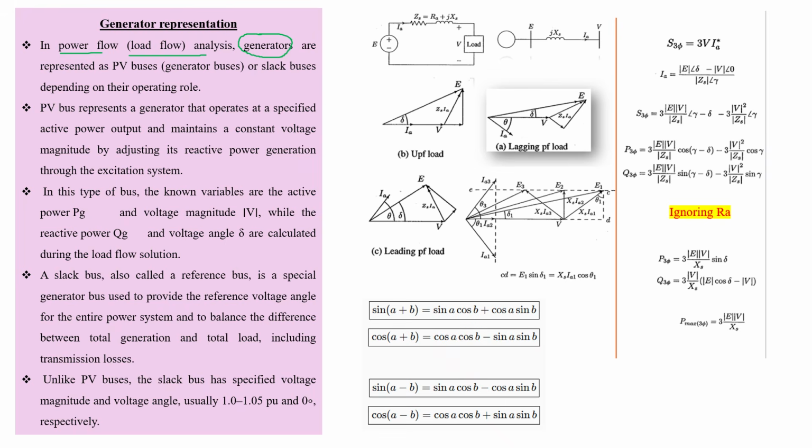circuit theorems. Based on the role in a power system, we can classify a generator as a PV generator, where active power and the voltage are specified, whereas reactive power can be calculated by using a power mismatch iterative method. In addition to that, we will have a slack bus.